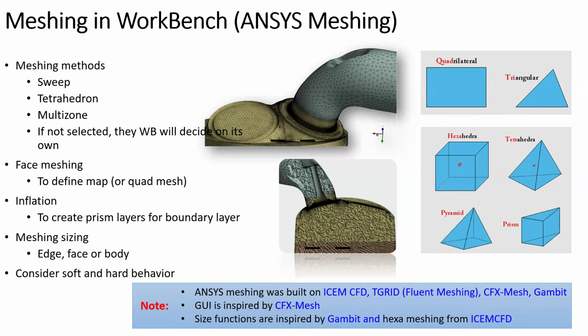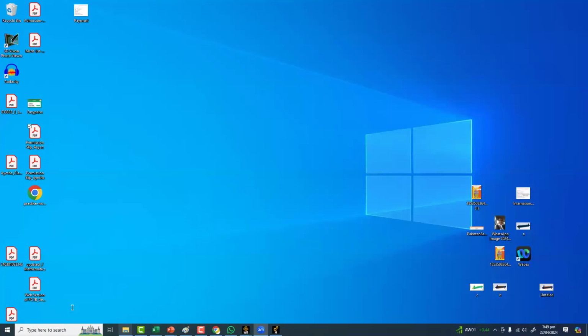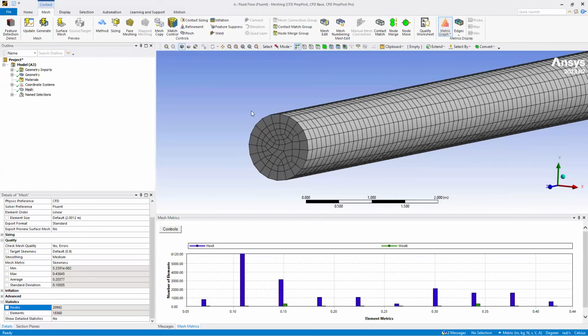And also there are nodes on the boundaries. So where these cells are intersecting the boundaries, they will be having nodes also there. So that's why nodes may be slightly different than the number of the cells. So if you take a look here, you can see this thing. The number of nodes are 20,000, number of elements are 18,000, because we have the extra nodes on the faces, like on these boundaries. Okay.